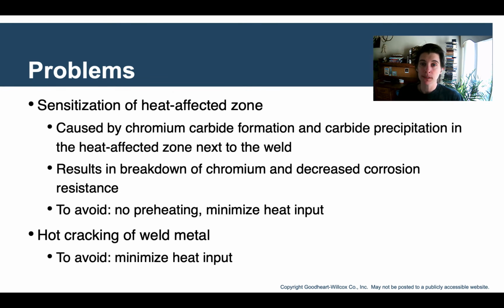So the main problem with stainless steel is the sensitization of the heat affected zone. Remember that the heat affected zone is everywhere around the weld area where the heat has traveled to. Because stainless steel is more conductive, that heat affected zone is going to be larger. It travels faster throughout the whole material.